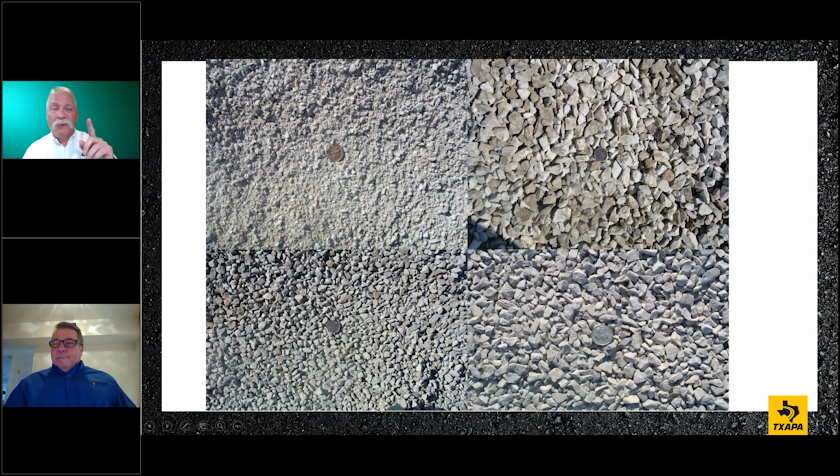Hey, Chuck, on the bulkheads, the bulkheads are not meant to add more storage, because if you overrun the bulkhead, then you're going to contaminate the pile next to it. So that's another good thing to watch: make sure those are kept below whatever bulkhead or bin height extensions are in the stockpiles, even in the bins in the asphalt plant. That's a good point. Putting a bulkhead up doesn't give you the opportunity to overload it so that they still become contaminated. That's a great point.